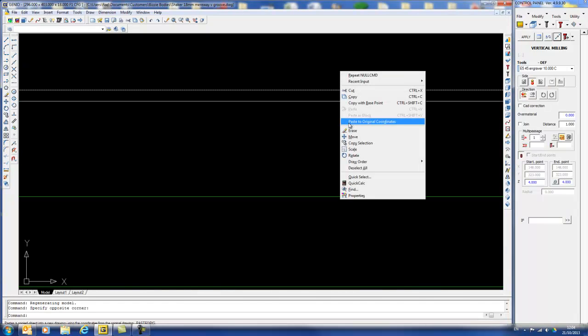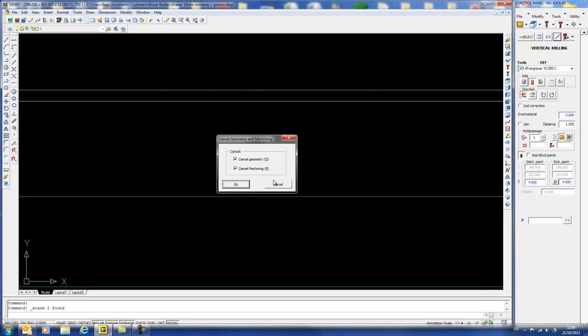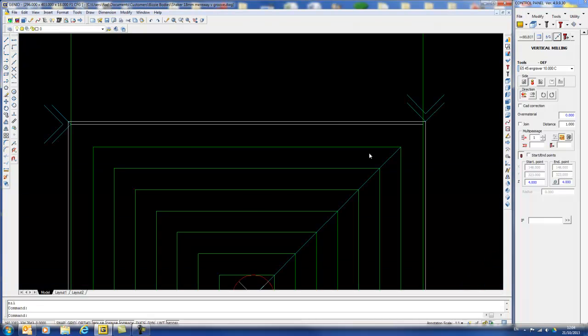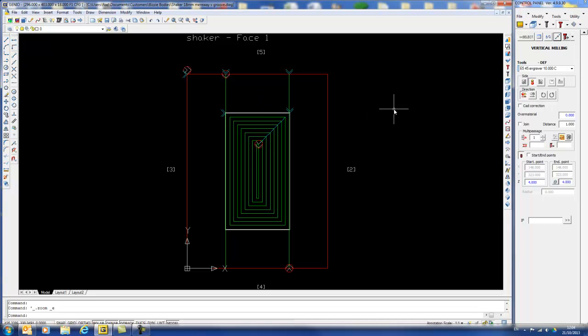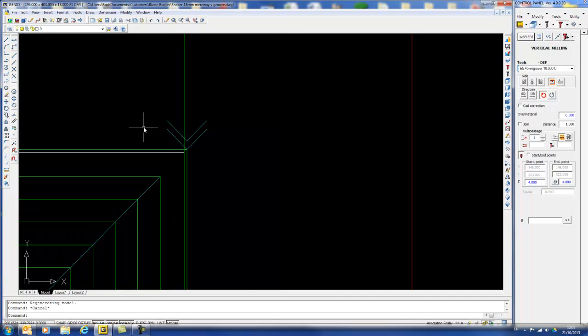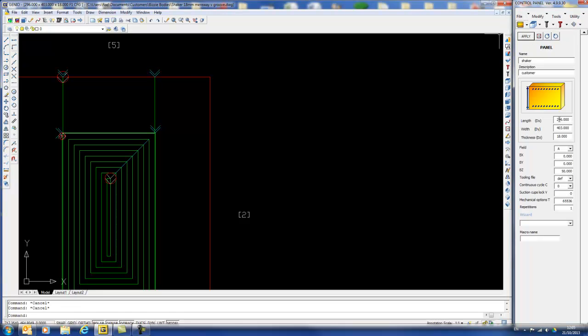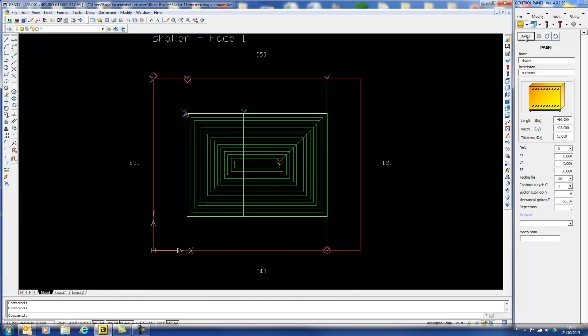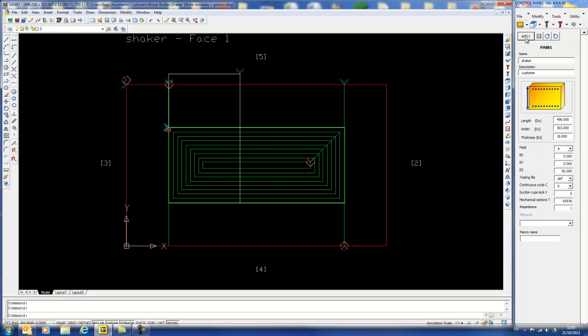Let's have a look. There were two geometries, so in theory now my parametric one should be on top, hopefully. Right, inside engraver, that one 4mm deep, that was red down there, so let me hope I can get it this time. And if we go and change size, we'll just try one at the moment. That has gone with it, and if we change that one there, that has gone with it as well.